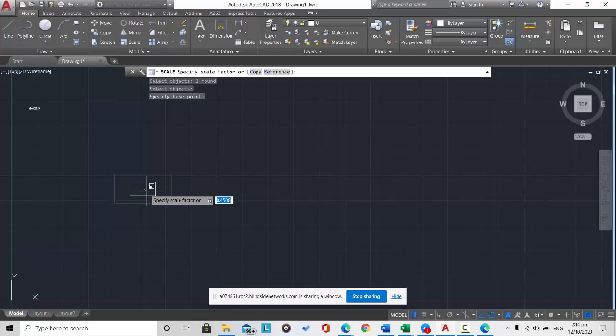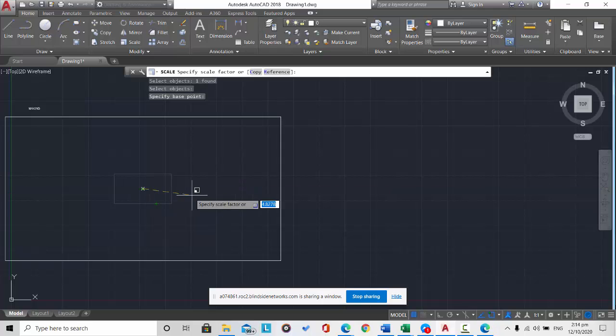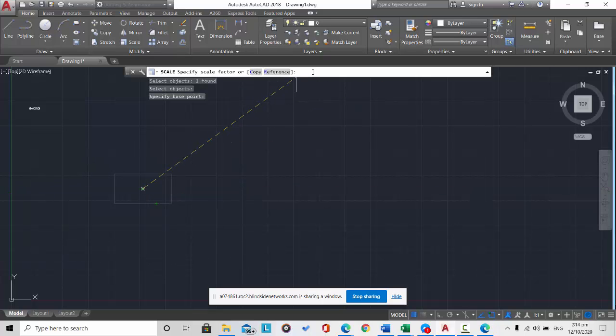So you will see now that the original object becomes transparent. The object is still there until I click the mouse, and you can see that you can specify your scale factor. For example, as I have said, if it is between 0 to 1, you are actually decreasing the object. Now, for example, 0.5, that's 50% scale. So the rectangle becomes smaller. The rectangle becomes smaller. Okay?